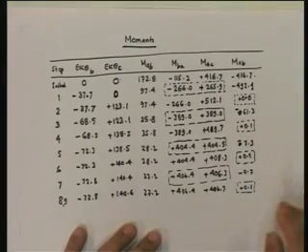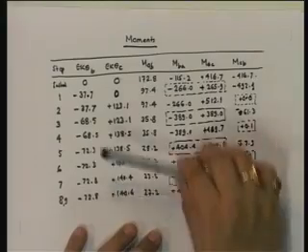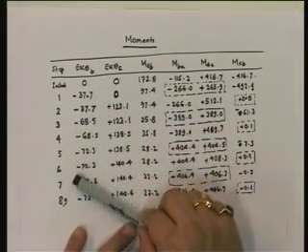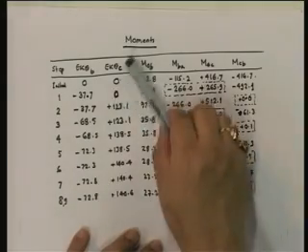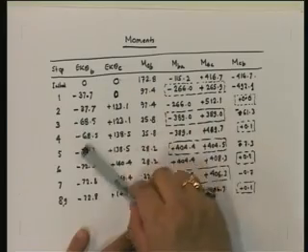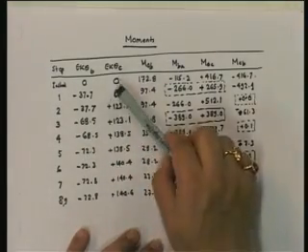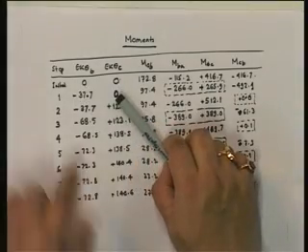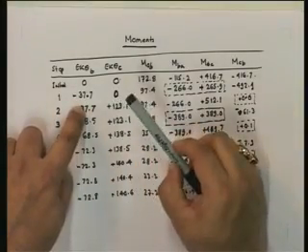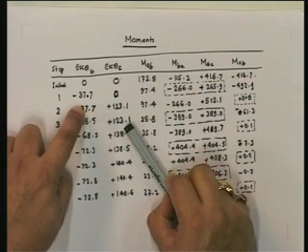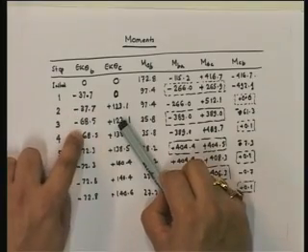So you understand the point. What you are doing essentially is clamping, releasing, clamping, releasing, clamping, releasing. So the whole procedure that you have over here is essentially a whole set of clamping and releasing. Physically clamped, release theta B, clamp theta C. Clamp theta B at the rotated position, release theta C. Clamp theta C at the released position, rotated position, release theta B.